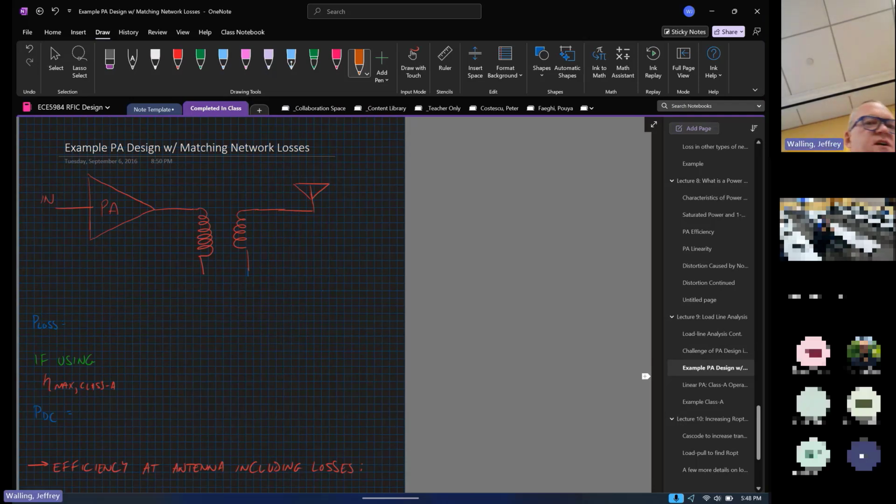Okay, so here is our new power amplifier circuit. We're going to do an impedance transformation, and we have our handy 6-to-1 impedance transformer. We can make this out of an LC network if we want to, but here we're going to use a transformer. And I'll show you in a few moments how to make a transformer in Cadence.